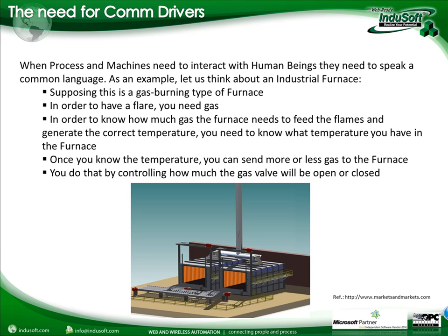So not to make it completely detailed, we're gonna just put that the flare will be controlled to reach the temperature that we want it to be. So for you to know the temperature, you're gonna need to have some kind of sensor to know what the temperature is, and you're gonna need somehow to control the gas valve that's gonna send the gas to the flare and keep the oven on the furnace on the temperature that you really want.